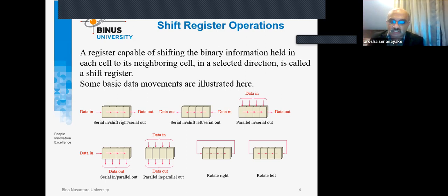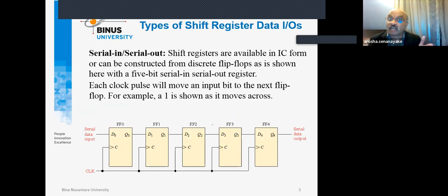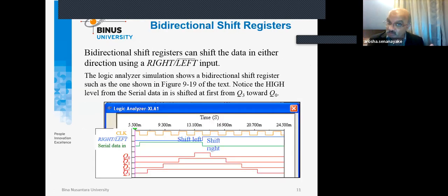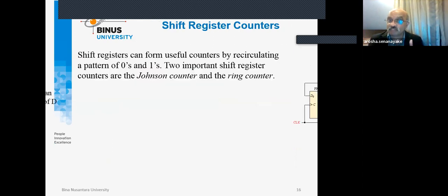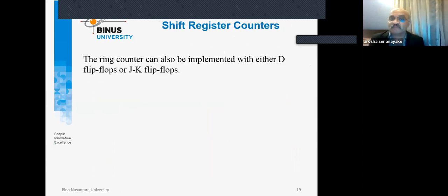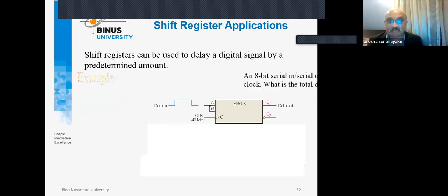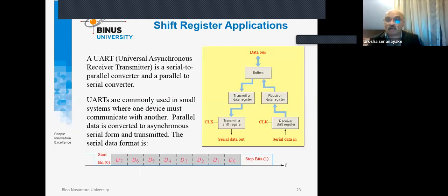Then we have to have a shift register that gets the bits 1 by 1 and produces parallel output to connect to the data bus. Very important, we should know it very well. There are an enormous number of applications, but here is what I refer to. The way UART transmits is like this: depending on the start bit, it starts transmitting actual data until it finds the stop bit. Then the stop bit means 1 packet of data is transmitted.